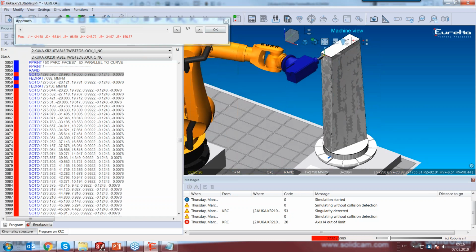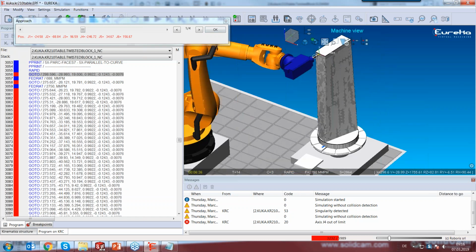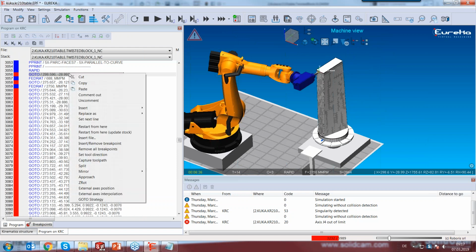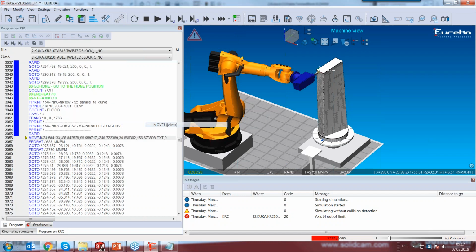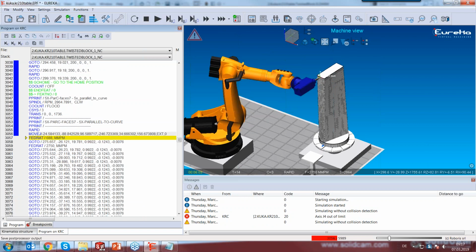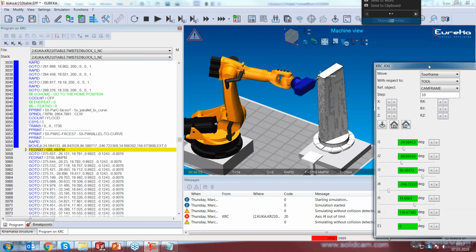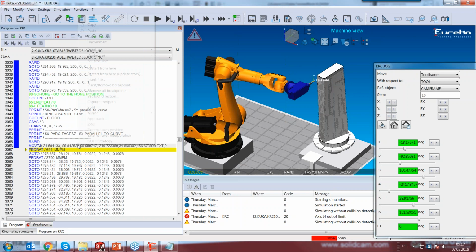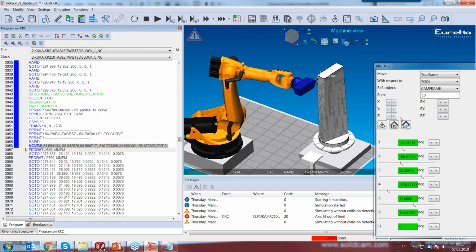Okay, and if it's in the moment for me to close on this point, I can also easily then replace as a joint, easily change this position by now modifying it with the axis, where I say, okay, move with the Z-axis more far away from the point, go back to this, go back.